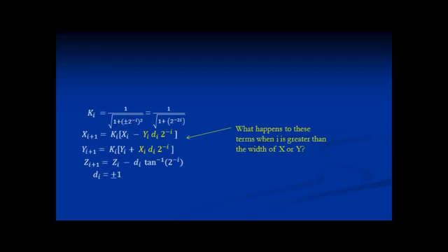So, if you have x and y variables of 4 bits, and your quartic is based on this, then doing more than 4 iterations will be useless and wasting time and resources. With that in mind, we'll create an arctangent table whose bit width is at least as wide as the x and y variables, and a length that is at least as long as the number of iterations. Thus, to eliminate the arctangent calculation, a small lookup table is used, 1 entry for each iteration, corresponding to the arctangent of 2 to the minus i.